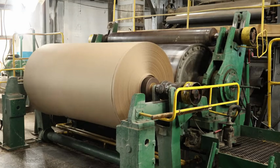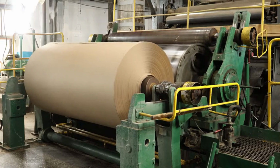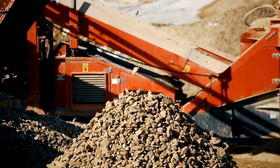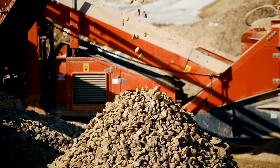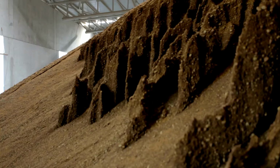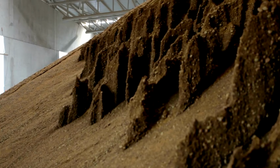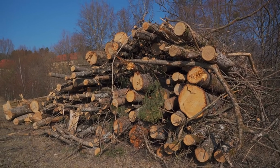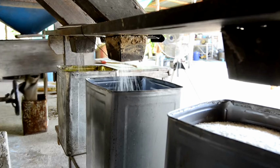The paper mill process involves multiple stages to convert raw materials, primarily wood, into finished paper products. Here's an overview of the key steps. 1. Raw material preparation. Wood sources, for example, logs, wood chips, recycled paper, are collected. Logs are debarked and chipped into small pieces for easier processing. Recycled paper undergoes deinking and cleaning to remove contaminants.